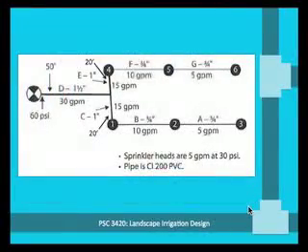So now let's make things somewhat more complex. Here what you've got is a sprinkler system with 2 lateral lines, and there are 3 sprinklers on each lateral. Each of these sprinklers requires flow of 5 GPM. So to run each lateral, a total of 15 GPM is needed at this point in the line.